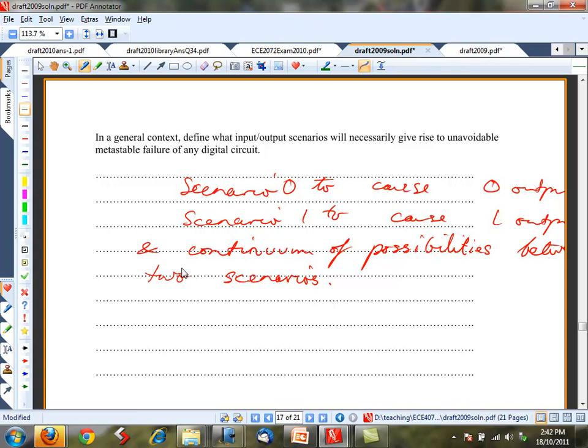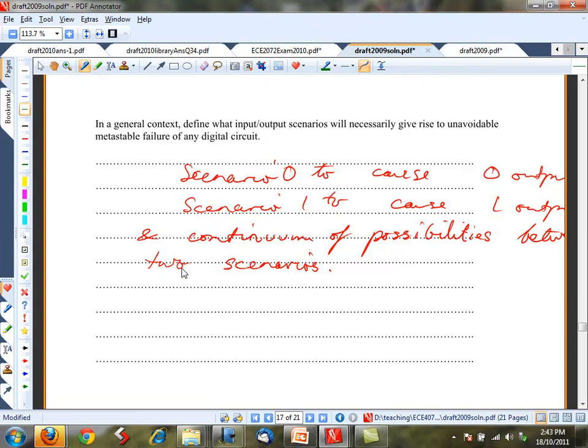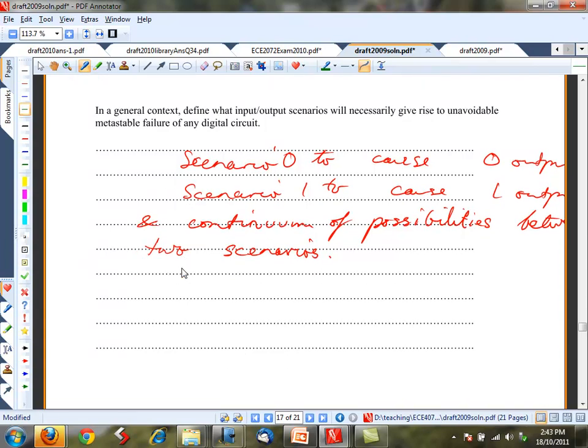So that could be the timing of two request arrivals. If they can vary continuously between those two possibilities, then somewhere between them is an unstable equilibrium point. So that can be proved with continuity theory in mathematics, in topology actually, that state will exist. So that means it's an unavoidable problem, and given that we've got a discrete output with continuously variable inputs, you can't get a perfect hardware solution to that problem.